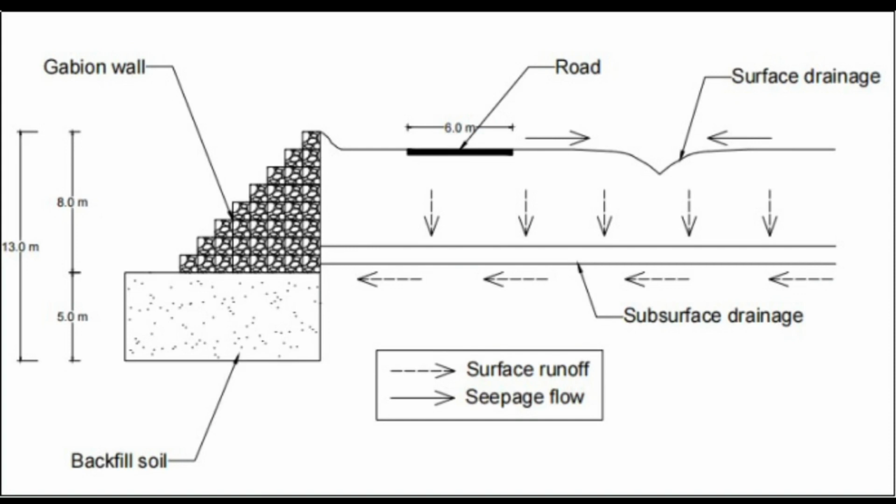are vegetation. Before beginning the process of designing a surface drainage system, a topographic survey of the area and a contour map of it should first be conducted. This can be accomplished through grid surveys, laser techniques, photogrammetric methods, or some combination of these. As a record of these permanent improvements, make sure to keep copies of the contour maps as build plans and profile drawings. These resources will prove to be extremely useful in the future when it will be necessary to regrade the channel or reshape the ditches.